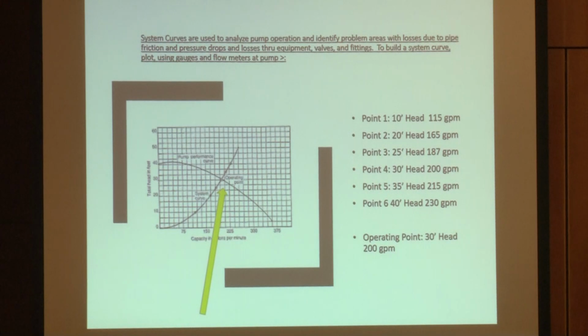So you have to take these measurements and then plot this operating curve to see how it's working at that operating point. This is something that we do a lot, and basically it just confirms that the engineer's design is working properly. As long as we're getting within 5 or 10% of that engineer's design as far as the pressure and flow requirements, then we're good to go. And again, we make the adjustments to get there, so most of the time we get there. We rarely see problems with pumping systems not meeting the specifications.